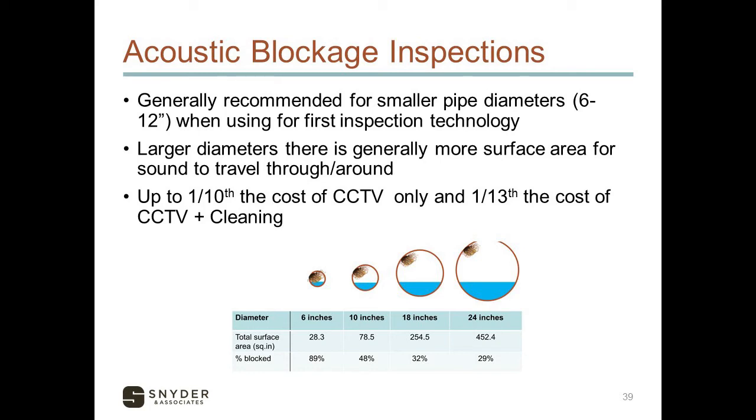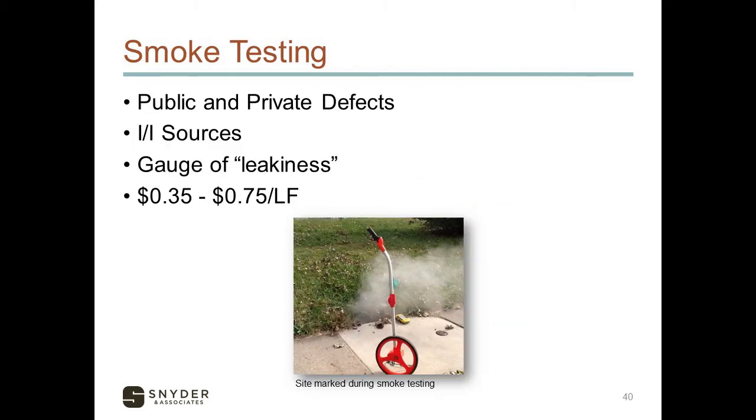I would just stress some caution when you're basing improvements off of just the acoustic testing. I would feel that this is more of a preliminary effort to understand where a more detailed analysis in your system should take place. We're going to be doing smoke testing on public and private systems to identify defects, looking at trying to find those I&I sources such as roof drains or surface voids.